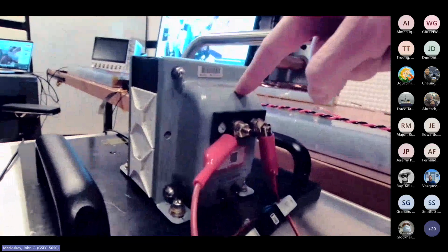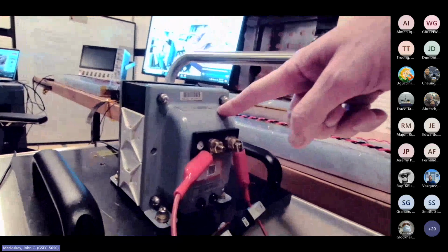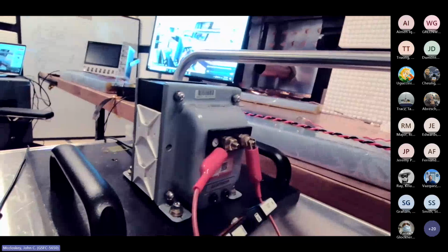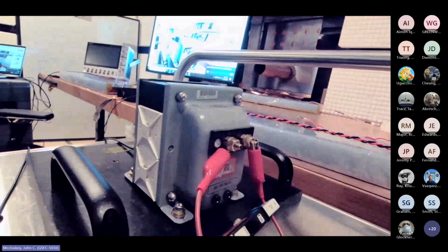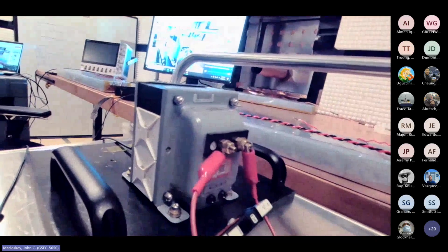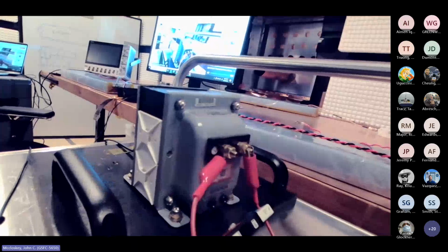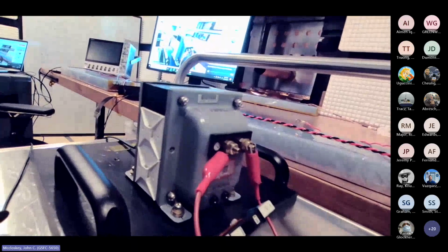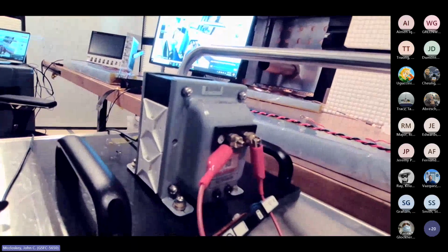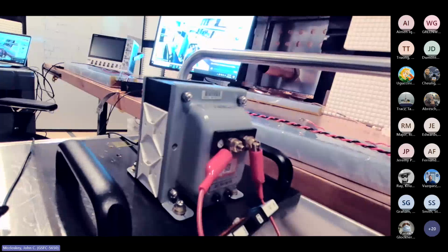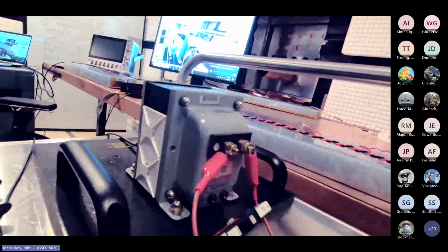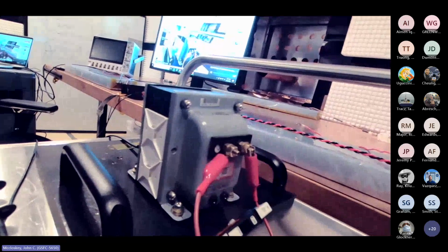Because if not, you're just getting the full about 1 millihenry inductance of the secondary coil in series with the power feed, and that can and has been shown to cause some instabilities. Like you can get significant ringing during power up, and you can stress or damage the input stage of your EUT, and you don't want to do that.